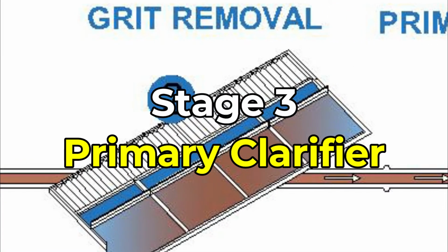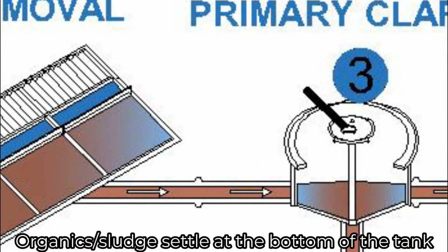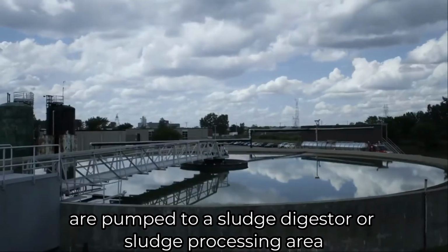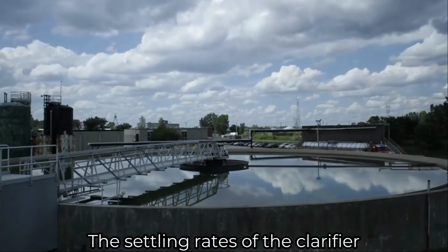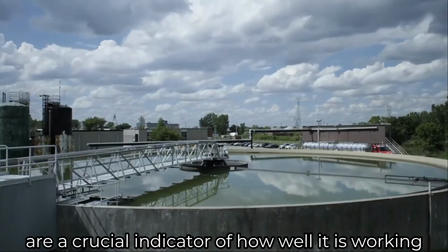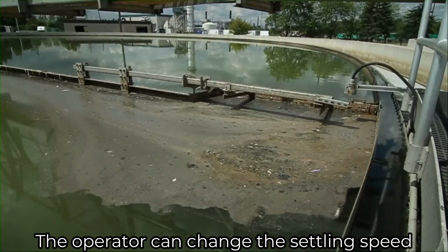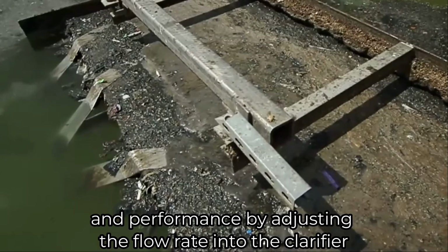Stage 3, primary clarifier. Organics or sludge that settle at the bottom of the tank are pumped to a sludge digester or sludge processing area, where they are dried and hauled away. The settling rates of the clarifier are a crucial indicator of how well it is working. The operator can change the settling speed and performance by adjusting the flow rate into the clarifier.